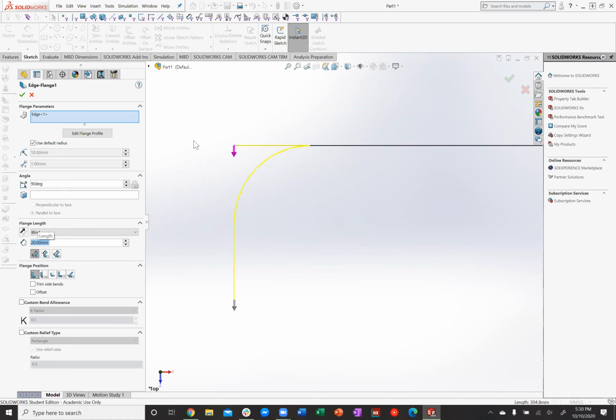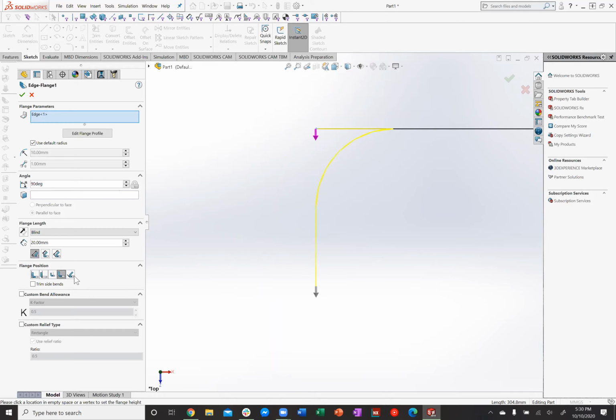Okay, like I was saying, see how the flange here is lined up currently with our previous extrude. That can be changed here, so you can have it lined up with the outside of the material thickness instead of the inside. It's very subtle movements here because this is a thin material. You can also extend it if you want to start the bend after the extruded material that we made. If you need this entire length to be flat, you can use different options here for different needs.